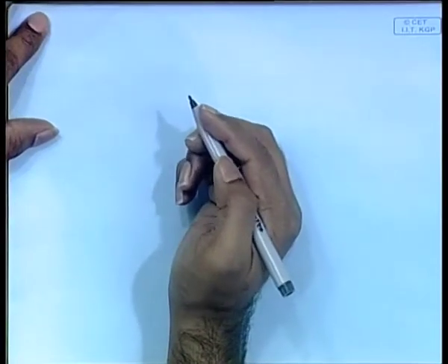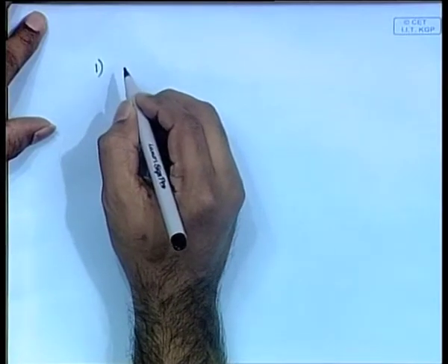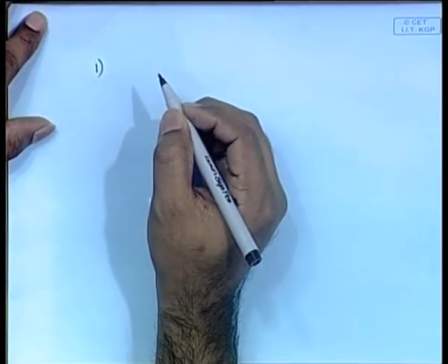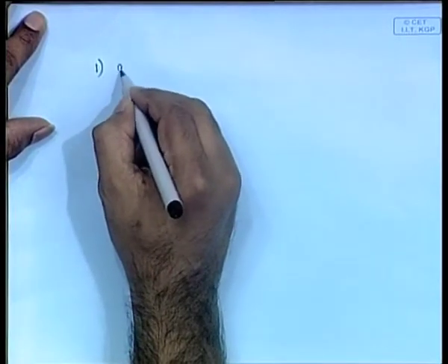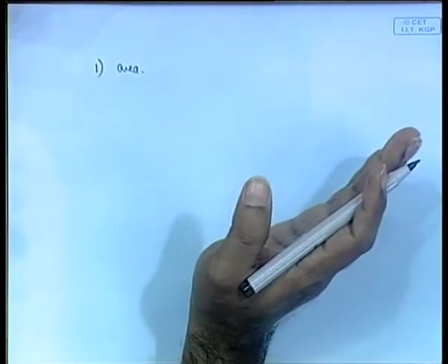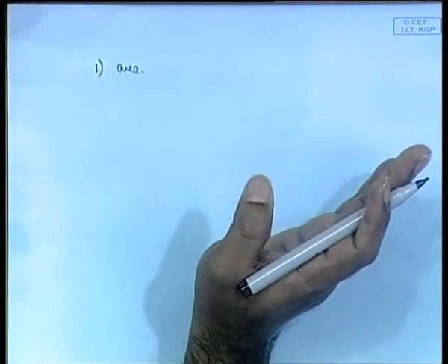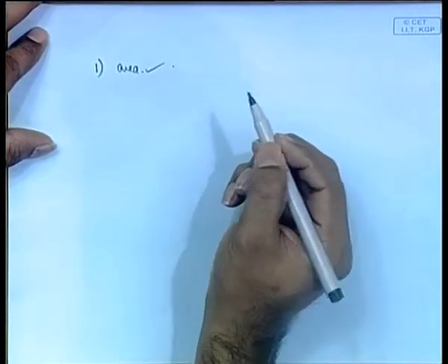So, just to clarify, a couple of formulas that you definitely have to be able to do. First thing is, of course, given the GZ table or the GZ curve, you should be able to find the area under the GZ curve. You should know how to do that. It's very simple. You are just going to Simpsonize the thing and you get the area under the GZ curve. So that you should be able to do. That is the first thing.